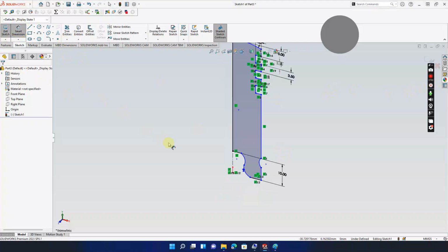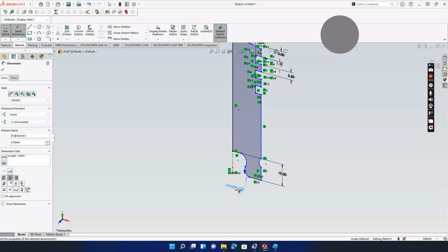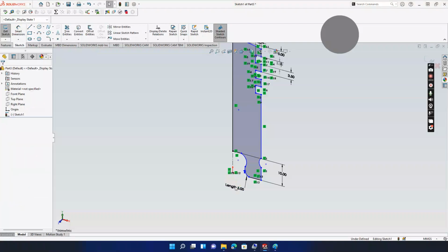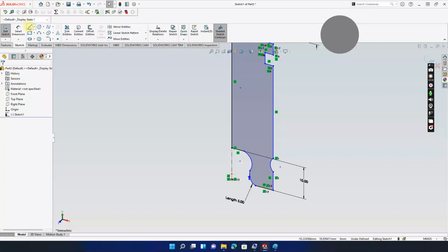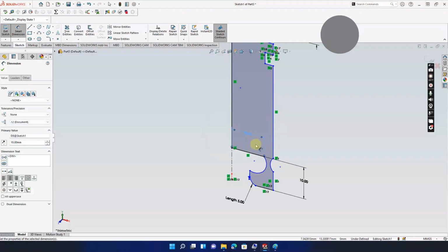Let's add a smart dimension to this. It says that's a radial distance of 5. Okay, adjust it to 5. And this is also going to have, okay, what else are we having right here? This is going to have a radial distance of, say, 10. So meaning we have a lot of things to actually adjust right over here.